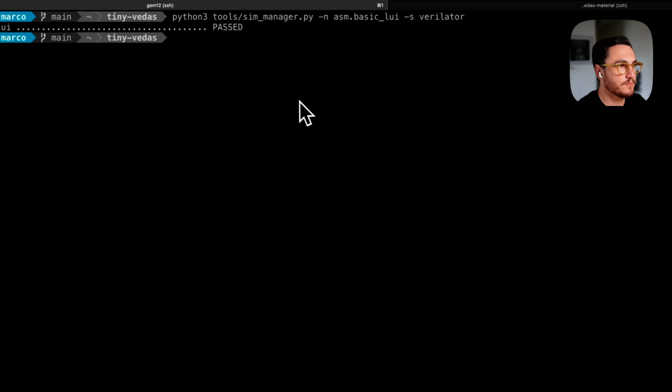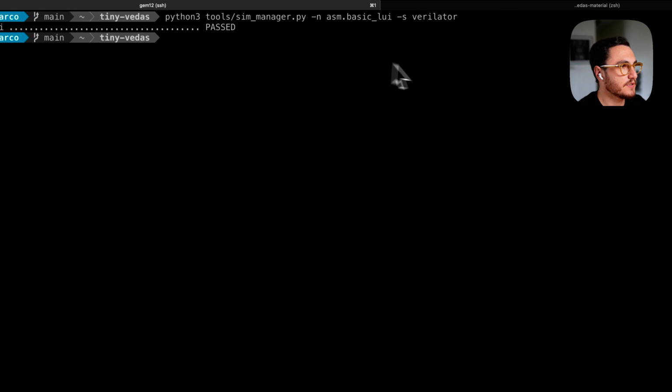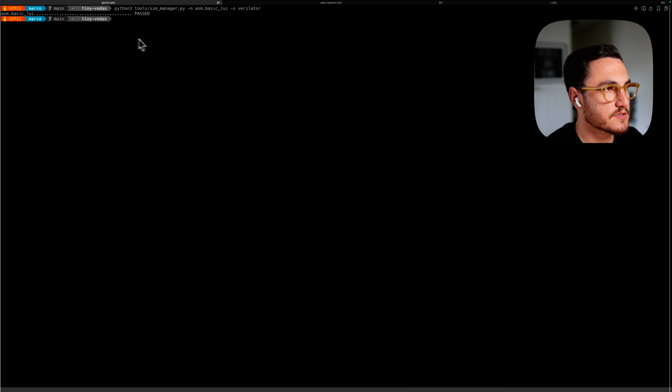So we fixed the bug with a very fast decode session, but that's basically how you find bugs. You get at the output, you trace it back, you see what the reference spec tells you, see if you made some implementation errors, and that's pretty much what you should do.